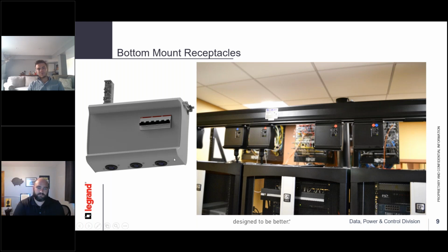Yeah, so guys, keep this in mind. We can't do every receptacle on the bottom. Obviously we have size restrictions. We can't put a 560 pin IEC connector on the bottom, like a pin and sleeve. There are some units we can. It wouldn't be in an E50, but there may be some sheet metal enclosures that we can do that in. If it's an absolute requirement, let your reps know, and we'll walk through it with you and figure out what we can and can't do.